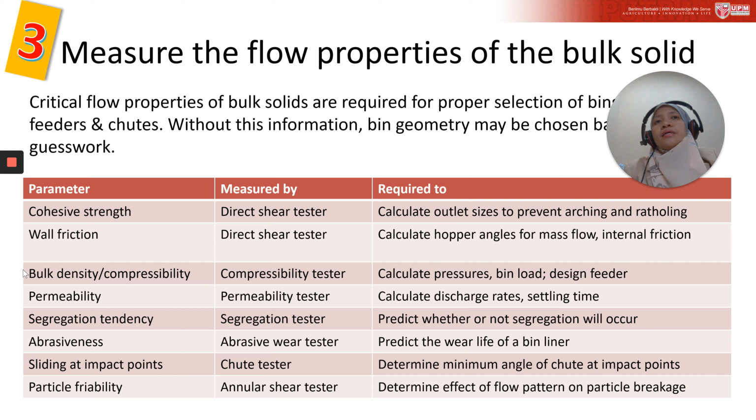All right. Then step 3. Okay, step 3 is we need to measure the flow properties of the bulk solid. A good practice is to measure the flow properties of the bulk solid. Every time you receive a new raw material, you must do the test.